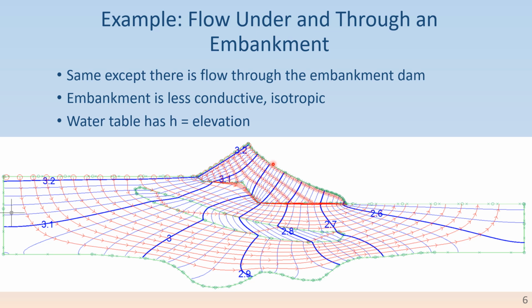And in this case, I've said that there's no appreciable recharge coming through that, so it's set to a 0 normal flux along that boundary. And then there's an interdomain boundary here that separates the embankment from the underlying more permeable sands. The sands and then this siltier lens that's less conductive still have the 8:1 horizontal to vertical conductivity ratio, but the embankment itself, having been placed and manufactured essentially, is assumed isotropic.